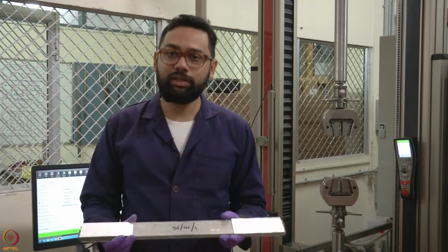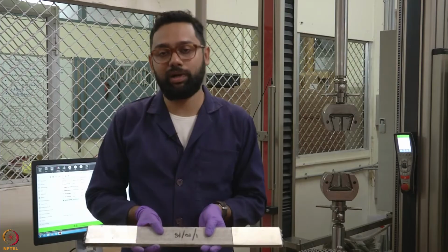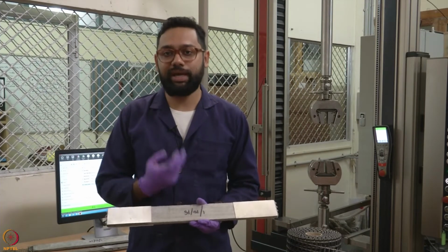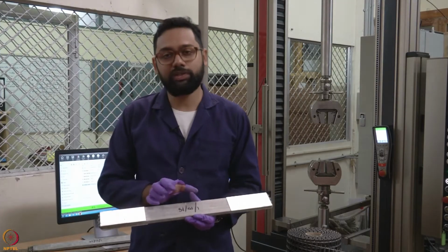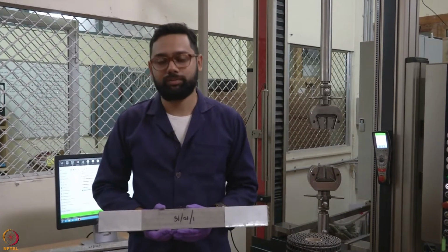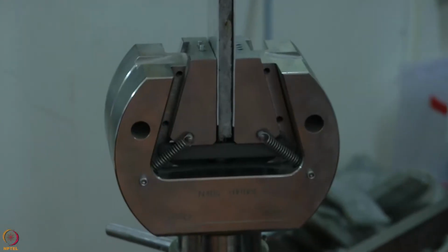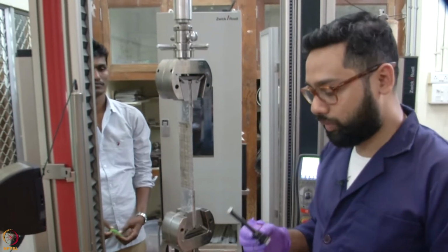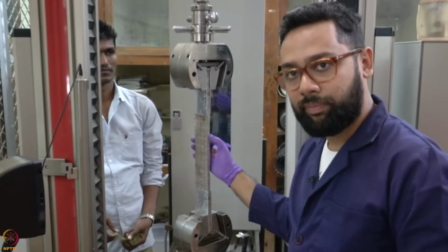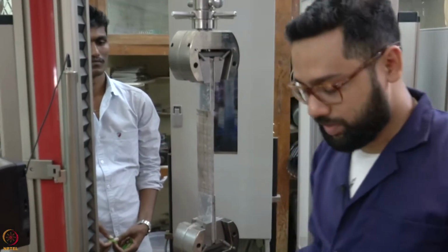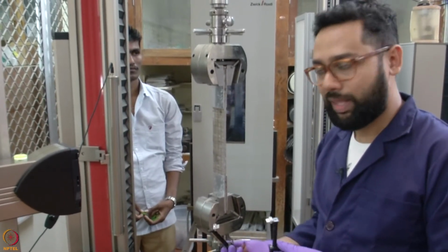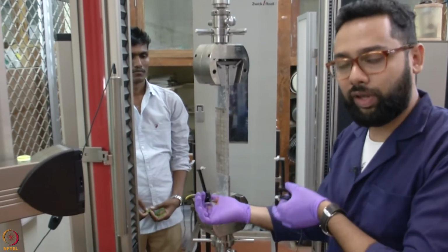The gauge length for the uni-axial tension test is a 200 mm gauge length as per RILEM standards. We will be using a combination of two extensometers: one is an axial extensometer and another is a video extensometer. With a combination of these we will try to find the strain variation or displacement in this material with respect to the load acting on the element. This is a 100 mm axial extensometer, a contact type axial extensometer. We attach it to a 100 mm gauge length on the specimen, and it is a dual axial extensometer, meaning it has 2 axial extensometers, and we get an average of the displacement from the 2 sides of the specimen.